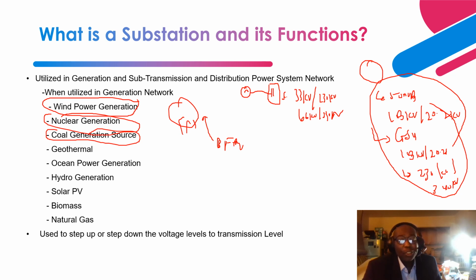And basically, it's a mixture of steam and water. As it rises up and goes through different reheat sections, it gets reheated, right? After reheating, you obtain a very dry steam, which is about 96% dry and about 4% moisture, right? So this is fed into a steam turbine generator, and the steam turbine generator produces electric power.